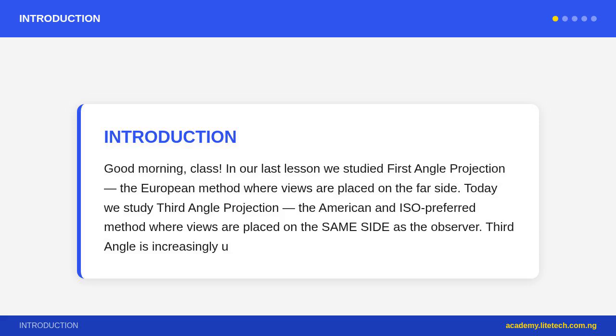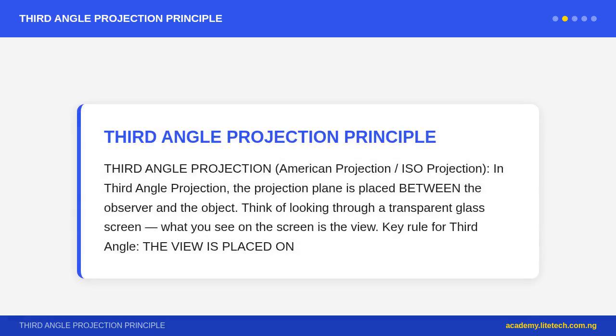Memory aid for third angle. Third angle, the view goes toward you, the projection plane is between observer and object, like a transparent screen. Third angle symbol, a truncated cone symbol with the small end on the right, the cone viewed from the right gives the small circle on the left. This is the opposite orientation to the first angle symbol.